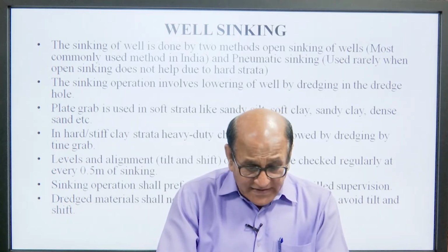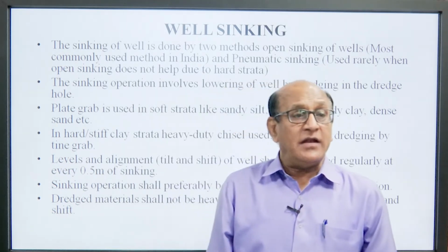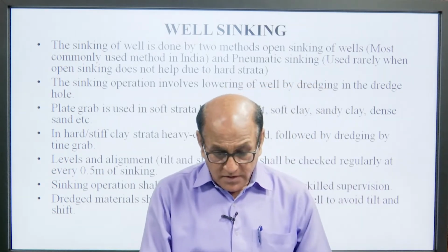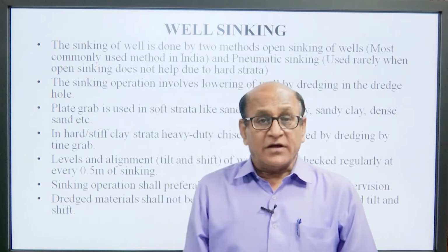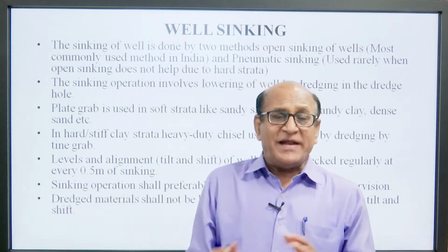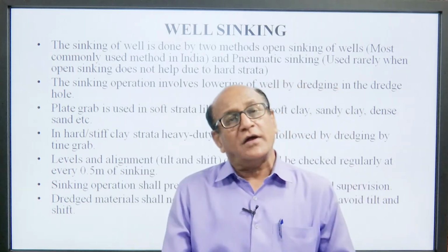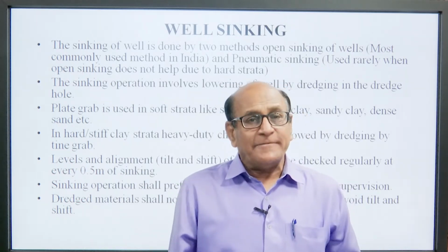Dredge material shall not be heaped on one side of the well to avoid tilt and shift. Suppose we are dredging the material and placing it just on the side of the well steining.